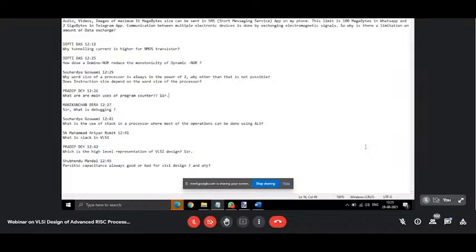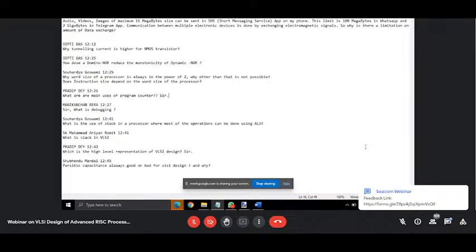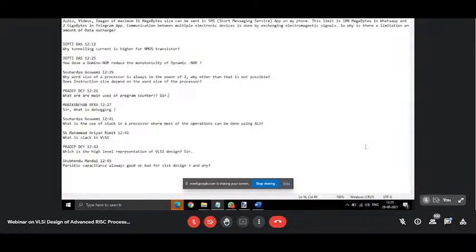These hazards will be there for asymmetric paths. When you design the VLSI, asymmetric means the AND gate's upper input goes straight away, but the lower one has to go through a NOT gate, so it takes some time. When you design complex logic functions, there will be many such problems. These timing fixations have to be taken care of, and there are certain techniques to solve this hazard problem. These are called timing hazards. Yes, understood. Got the point. So that's it.